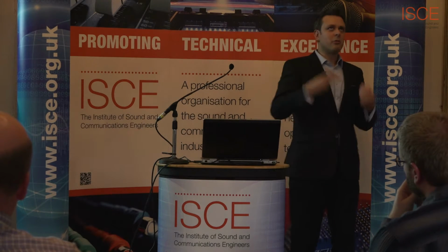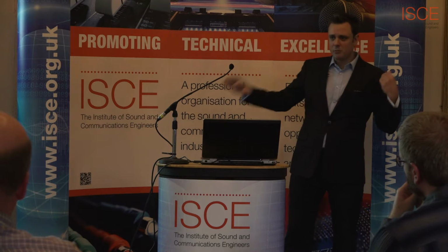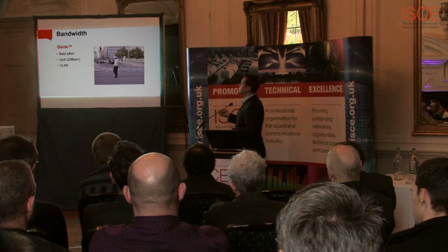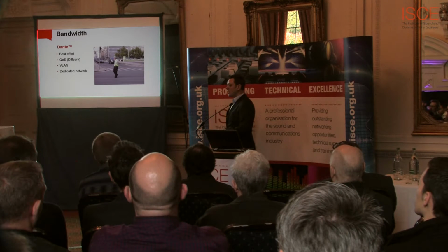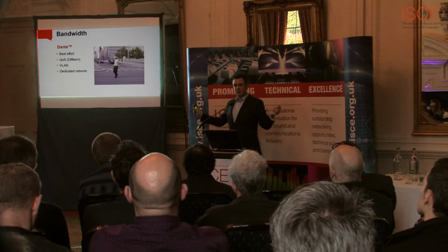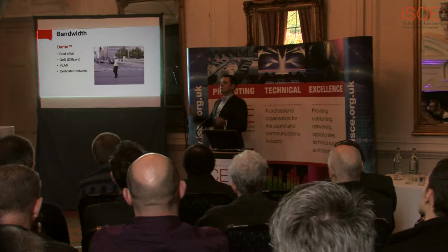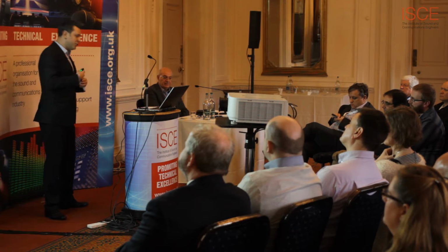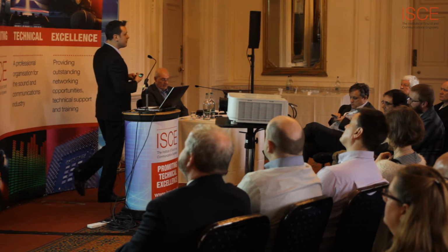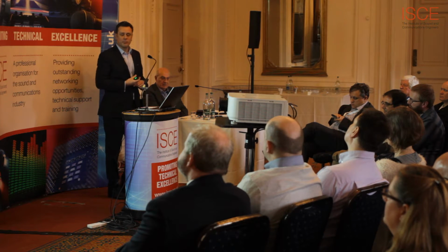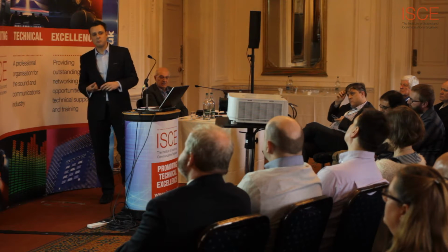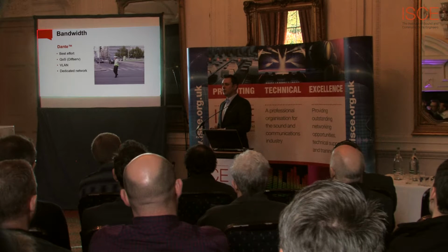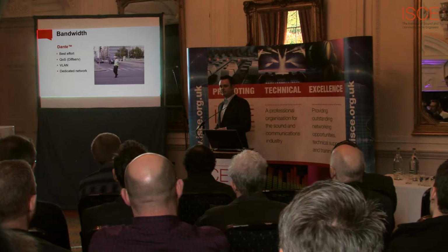The recommendation is that above 32 channels on a 100 megabits per second network, you must remember that. If not, create your own VLAN or your own dedicated network, and again, make sure that the bandwidth is there. If you fail to do so, everything is probably working beautifully, and then suddenly the whole office receives an email with a nice link to the latest cute kitten video on YouTube, and your whole audio starts going down because the whole bandwidth is gone.